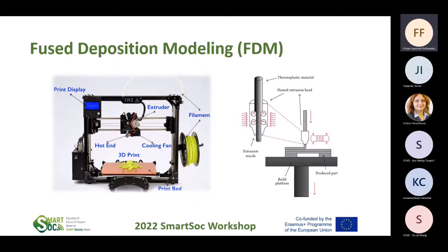Okay, just come here. So this is the raw material. The printing head is there. There is a nozzle whose diameter is about 0.4 millimeters. It is liquefied, so the material is quite hot when it leaves the printing head.